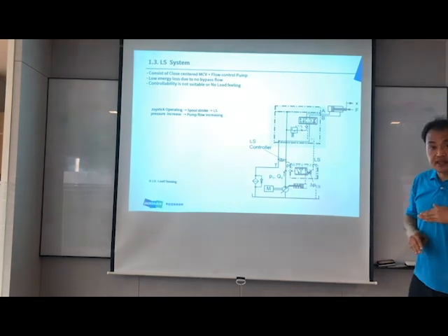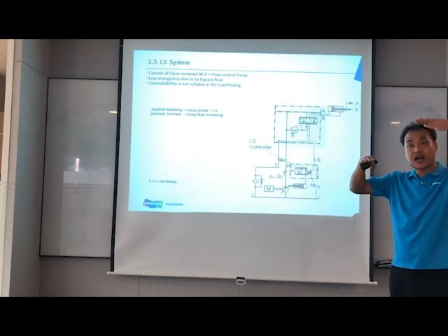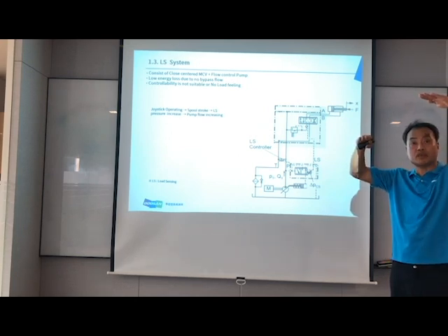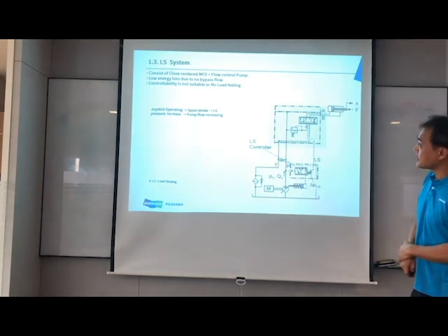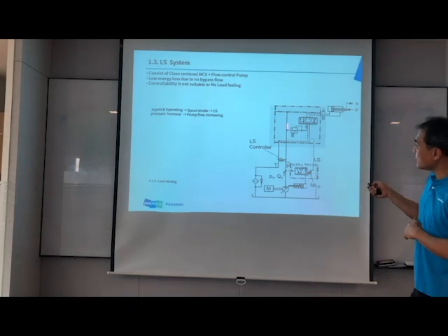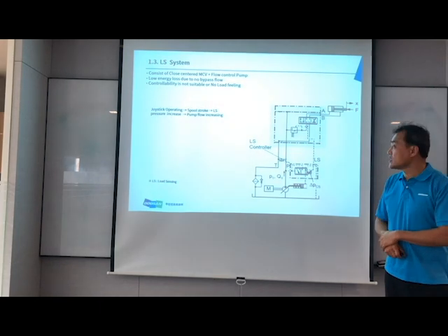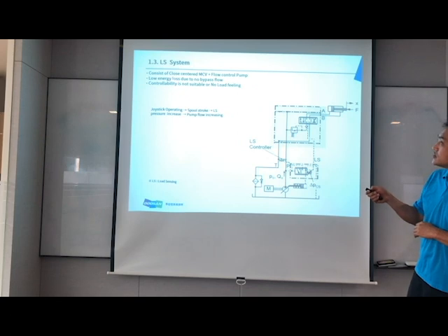Once again, in the LS system, the basic pressure is the LS pressure. Always some specific value of higher pressure is maintained by the pump. How? Flow. Reduce flow for 20 bar, increase flow for 20 bar, and stop like that. This is the LS system. That's why there is low energy loss, because little oil goes to the tank. The pump always discharges the oil demanded by the cylinder, with no more going to the tank. That's why energy loss is very low.